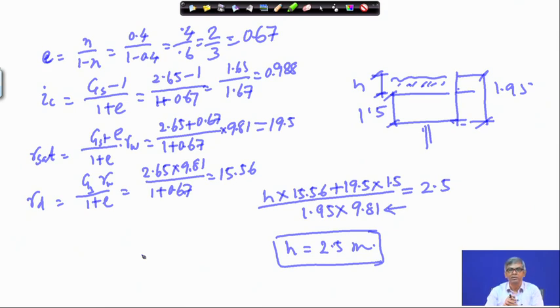Actually at that point, since I have not discussed the shear strength yet, I am not able to use that. Actually at the critical hydraulic gradient point, the soil loses shear strength, it becomes less, and because of that, if you put any load on it, it will not be able to support it. So it will be like a flowing condition. That I will discuss again later on. So this is another application, the second application, that is to achieve a particular factor of safety. That is the application I have shown here.